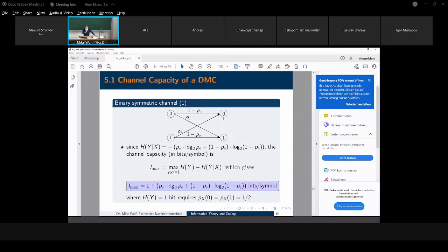Then you could also say, I use a kind of training sequence in the simplest case, and I transmit a stream of known information. And then, in this very simple case where it's just completely inverted, by means of this training sequence, you would know, in truth, I have transmitted a 0, but I received a 1. And always, if I transmit a 1, I receive a 0, then I could detect this from this training sequence, for instance.